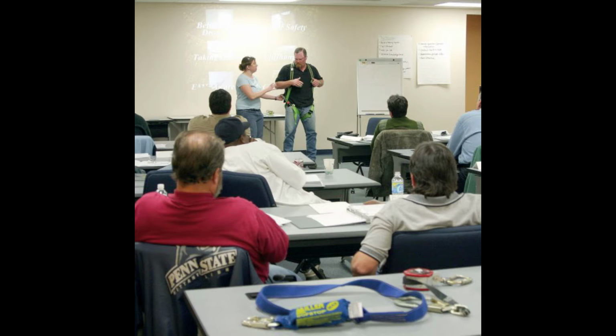the limitation on the use of mechanical equipment during the performance of roofing work on low-sloped roofs; the correct procedure for handling and storage of equipment and material, and the erection of overhead protection; the role of employees in the written fall protection plan; and the standards contained in OSHA 29 CFR 1926 Subpart M, fall protection. The foreman, manager of safety, or a contracted consultant trainer will identify all current and new employees who require training and will schedule the classroom instruction for these employees.